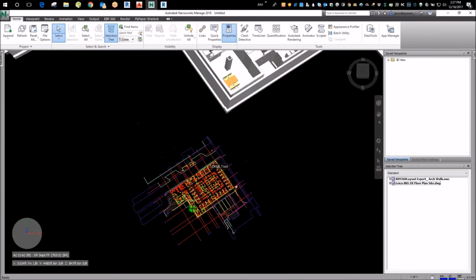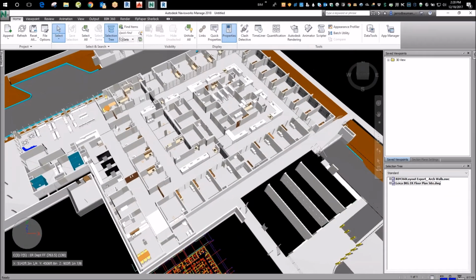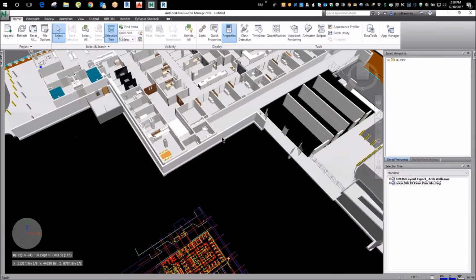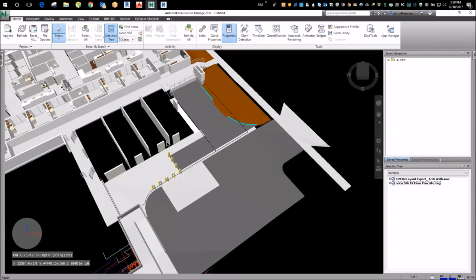Okay, I'll give you a hint. Like every project, surveyors also work in true elevation. How do they know if the finished floor of the building is getting put in right? This one is very critical. This hospital, where you exit or go into the existing hospital, is a foot higher. This slab has to be a foot lower, and then this make-ready building is even a different height than that. So surveyors work in true elevation.